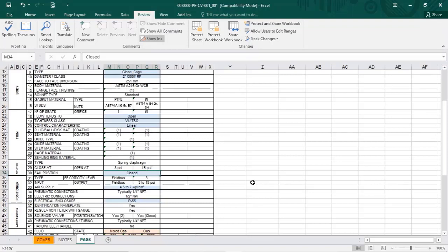And to make that decision, you need to know what is the purpose of your valve. So in this case, I'm controlling the flow to the customer. I know if my valve fails and it gets opened, I will have too much gas coming from the truck, and because of that the heat exchanging system will not be able to heat the gas.